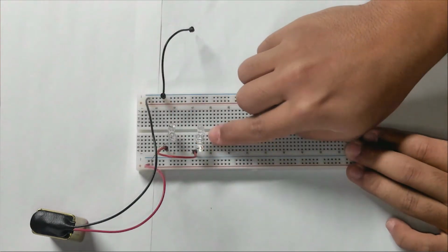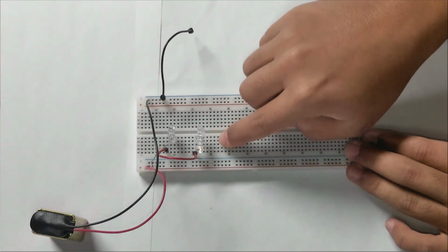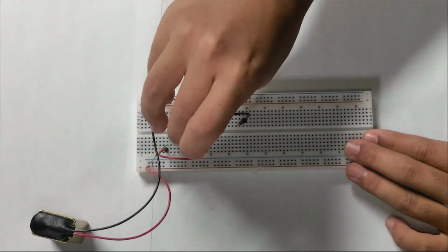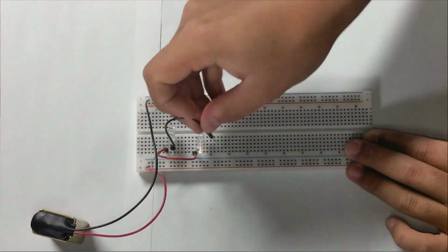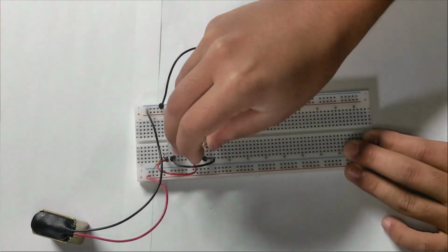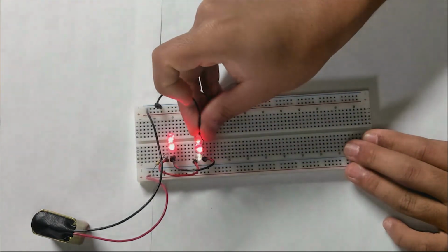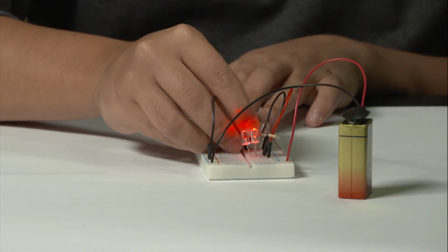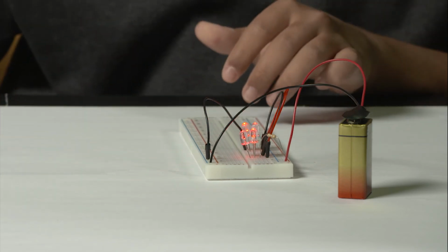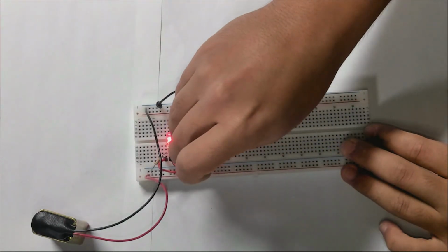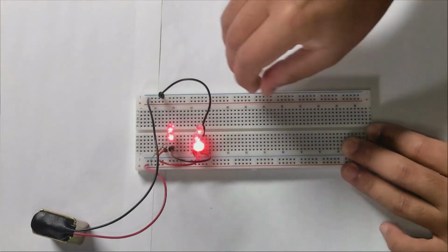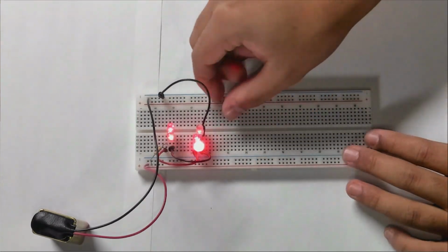And again, all of these LEDs have their positive and negative ends connected to each other. So to complete this circuit, we want to connect the negative side of the first set of LEDs to the negative side of the second set of LEDs. And we want to connect all the negative ends together. And as we can see, it looks like 4 of these LEDs have turned on. One of them did not. Let's try and replace this with a different one. There we go. So now we have 5 LEDs in parallel, and those are all lit up.